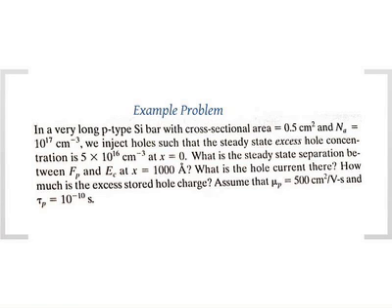Now remember, what does recombination mean? Recombination means the electrons that are floating around in the conduction band are captured and brought to form a bond with silicon. And they go out of the conduction band. An electron is lost from the conduction band, and an excess hole is there. Remember the physical meaning of what a hole injection means. It's basically pulling electrons out, which means you're removing negative charges, which means you're injecting positive charges. So essentially, on an average, that's the total charge that you are generating into the semiconductor bar per unit time.